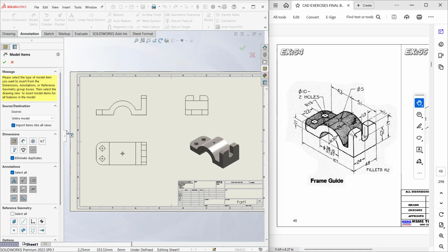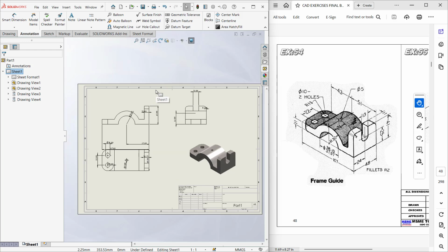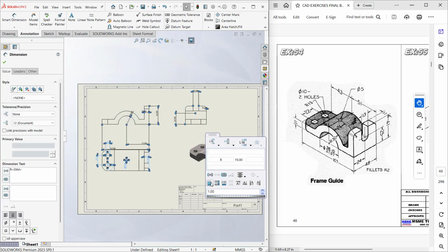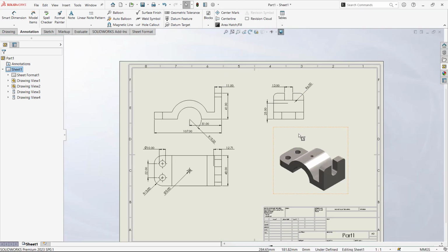Okay, and then if you want you can just select the origin, which can be accessed, even the construction lines also, and then click on the green check. Automatically the software will assign the dimensions, you could see, right? Now I would like to arrange them automatically. What you can do is you can select all the dimensions, and once you have this icon here, you can select this option, that is auto arrange dimensions. Automatically it tries to set up everything. You could see everything is perfect, right?